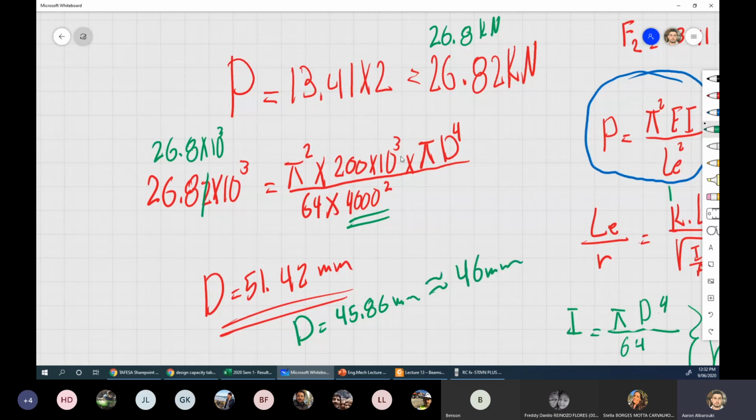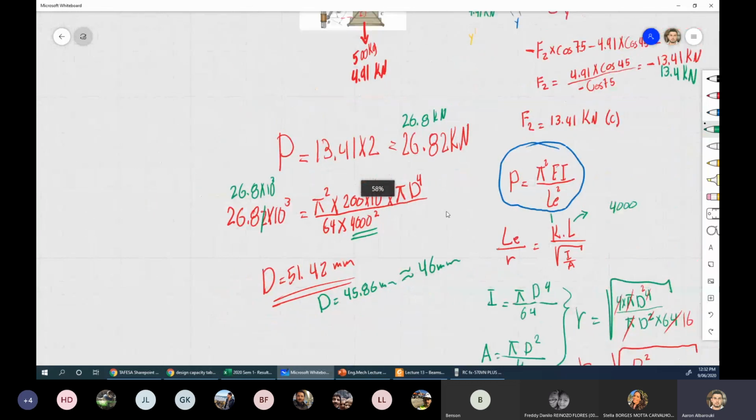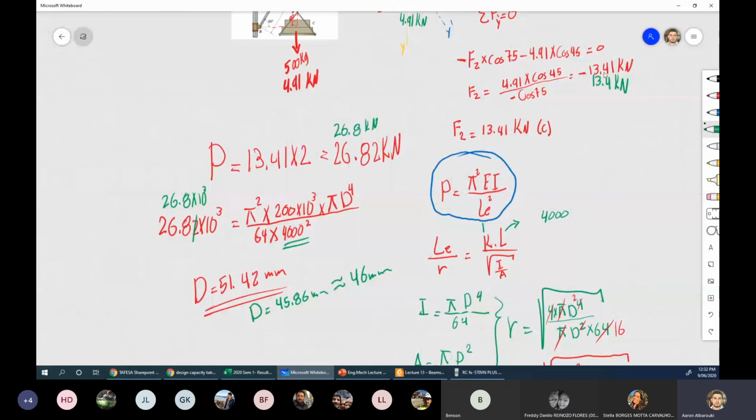So you understand, guys, when I'm initially calculating from this point onward, if I get a number, you've seen it, 13.409, I take it as 13.41, just slightly larger, because I know that will make me safer. And continuing this way, multiplying that safety by 2, solving the equation to the power of 4, that gave me a few millimeters larger. So if I'm the engineer designing this, I'll tell my client, your minimum diameter will be 52 millimeters, which is a slightly safer number than calculating numbers just on the edge. That's all it is. All good?